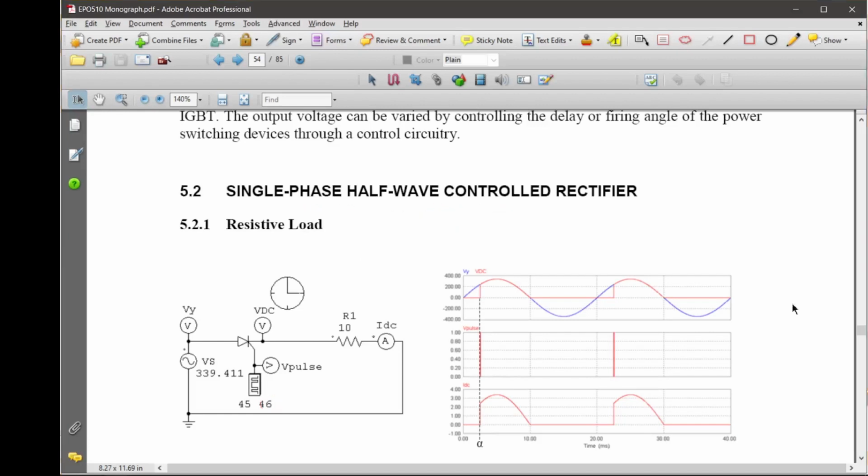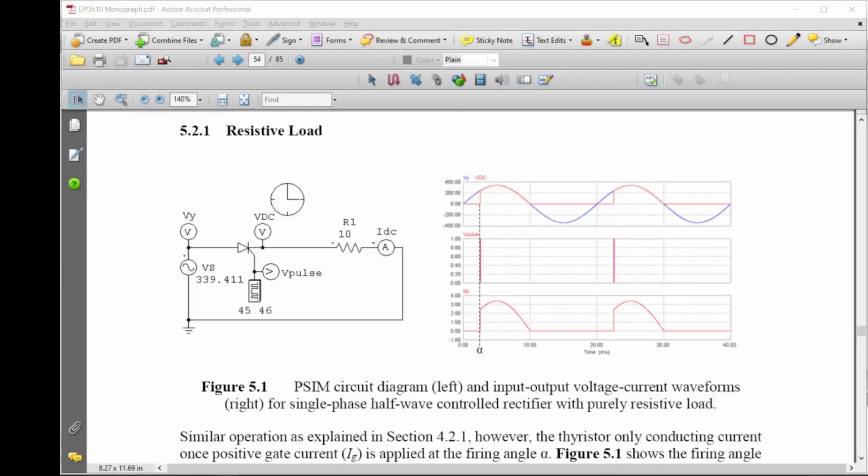Okay, right. So let's go further. Once we have this output voltage, then we need to look at the average. So the average is just integrate, okay, to get the output voltage. The average of the output voltage was what? We have this equation of Vout equals 1 over T, and then you integrate from 0 to T, and then the equation dt, is it? So now the lower limit becomes alpha, and the upper limit we have as pi, is it? So that point is pi, and this is replaced by 2 pi.